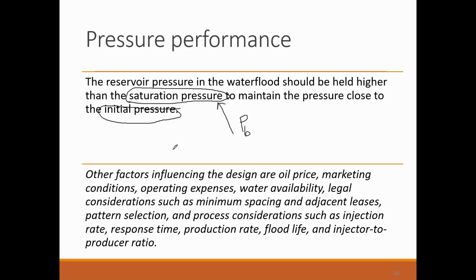And if I need to mention one more point, suppose this is a well and this is a wellhead. It is not always possible to take a static pressure, that is PS, or BHP. But on the wellhead, you can take the tubing head pressure. It is very easily available. So it is very imperative to see whether your THP is declining or not.